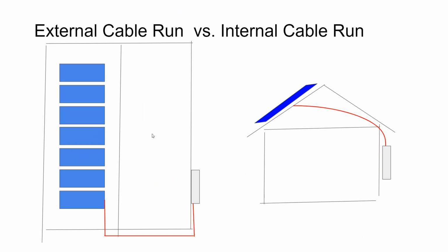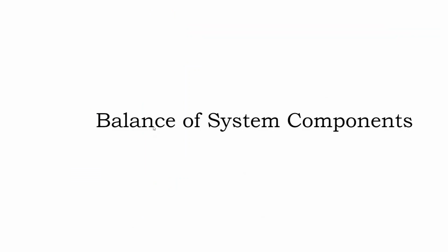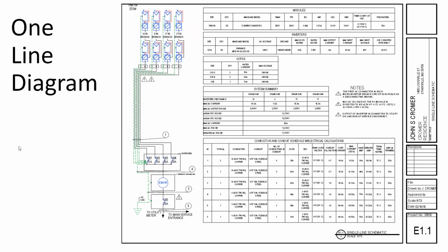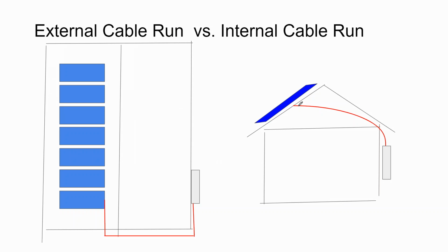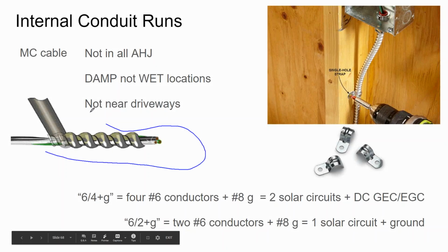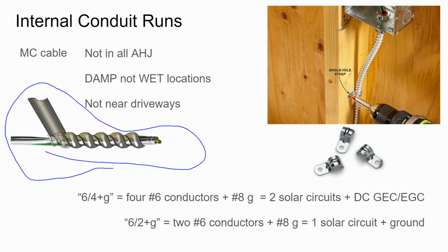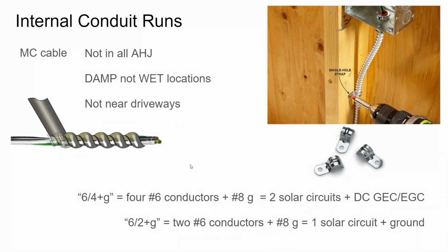Well, let's leave some closing notes. We talk about internal conduit runs and stuff in design classes, but for this home run circuit, the circuit between the array and the inverter down below, I'll generally run it through the attic rather than on the rooftop. And solar circuitry, unless you're using microinverters, which is AC, the DC circuits inside of buildings need to be in metal. So a lot of installers will just stay outside the building and wrap their conduit around. What I'll do instead is I'll specify metal clad cable for my cable run inside the house, and that'll give me that inside of metal qualification, but it's also flexible enough to run through an attic, and it's very easy to install. It's expensive, but it's easy.